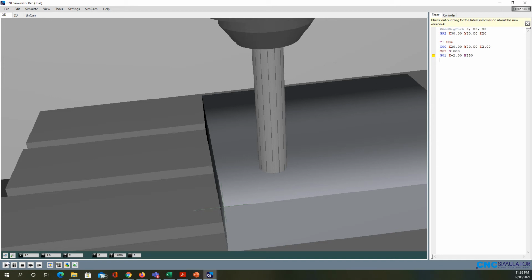Insert that. So now I'm going to repeat from the beginning. The cutting tool will come, and now it went inside the work part. Now my next location is going to be to the top here, which is going to be halfway in X, which is 50, and just below the end by 20 millimeters. So X50 and Y is going to be 80. Okay, and I'm going to keep the same feed rate. So I'm not going to change anything regarding the Z or the feed rate. So I can write that directly as X equal to 50, Y equal to 80.